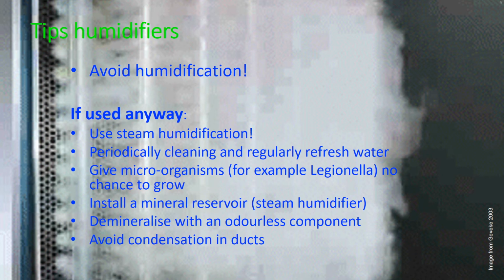In case of a humidifier with water, minimize the deposit and/or formation of minerals by making use of demineralized water or a good removal system, and refresh water regularly. Now, for all systems, it is recommended to clean regularly, every 6 months, dry or wet, or at the start and end of an out-of-use period.